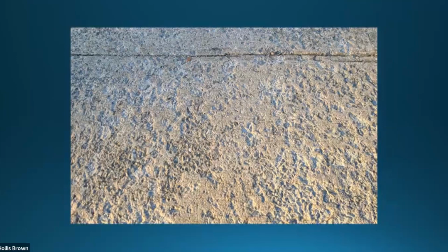So again, we're back to curing the concrete. And if you don't cure it properly, this is what you get. So we're going to go through a series of pictures here. Again, this is kind of a recap. The things that can cause this, there are many of them. One is very flat concrete that's not draining, too little cement, too much water. When it was poured too wet, and then not properly cured. All those things will weaken the concrete.